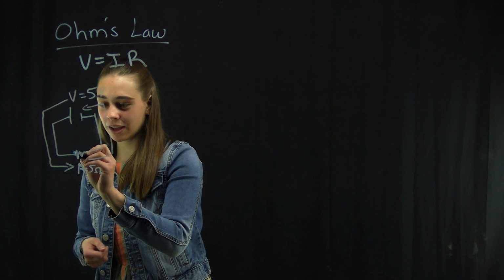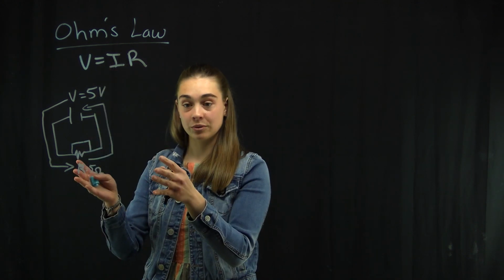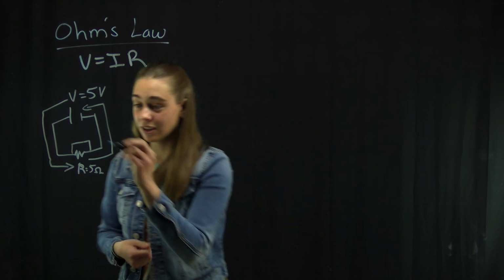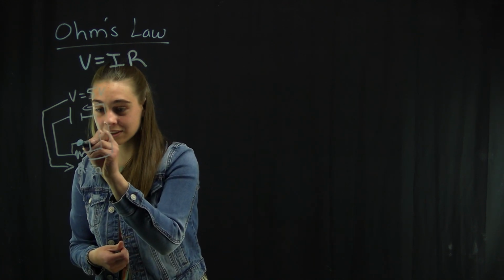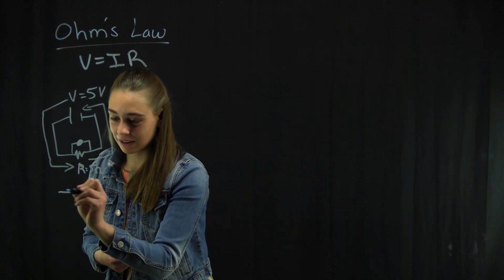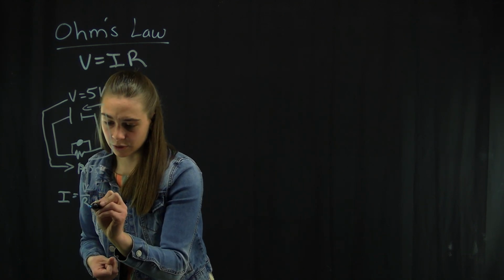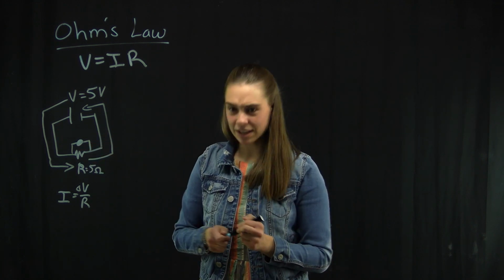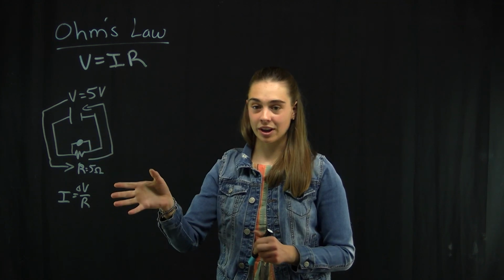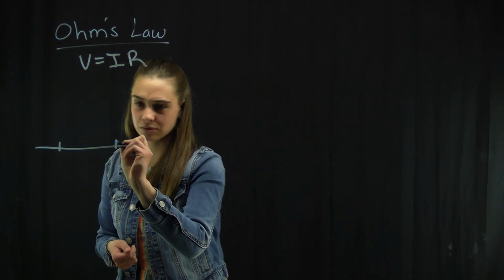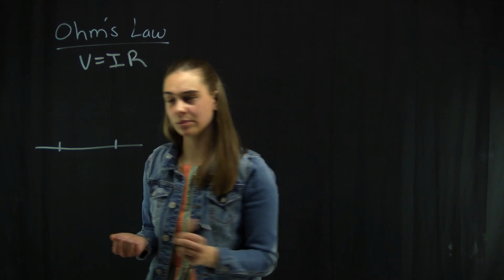And we can put a voltmeter over the resistor to find the voltage change over the resistor. So we'll have this little voltmeter. And from there, we can then find the current, V over R, or we can say the change in V from the voltmeter. Now, say instead of this simple circuit, we now have a circuit where we have these metal electrodes, which are just metal rods stabbed into the ground.